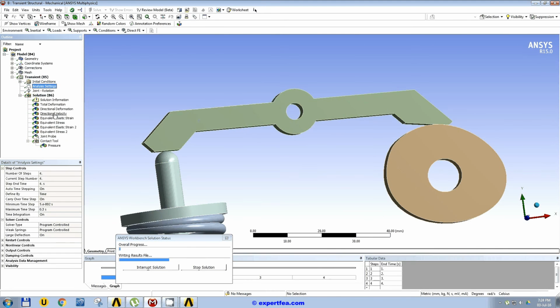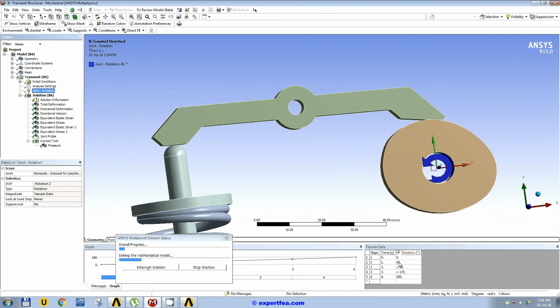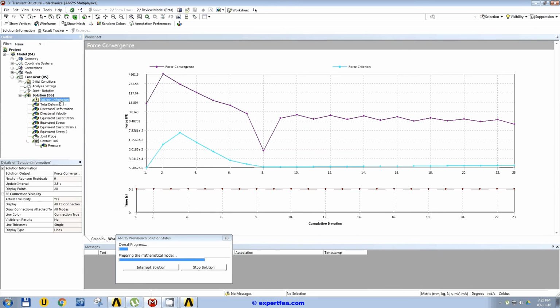And in ANSYS settings, making the time steps smaller, the time increment smaller, usually helps in convergence. Also, last but not least, the discretization, the incrementation of the load can be also decreased. So let's see what the solver is doing now.